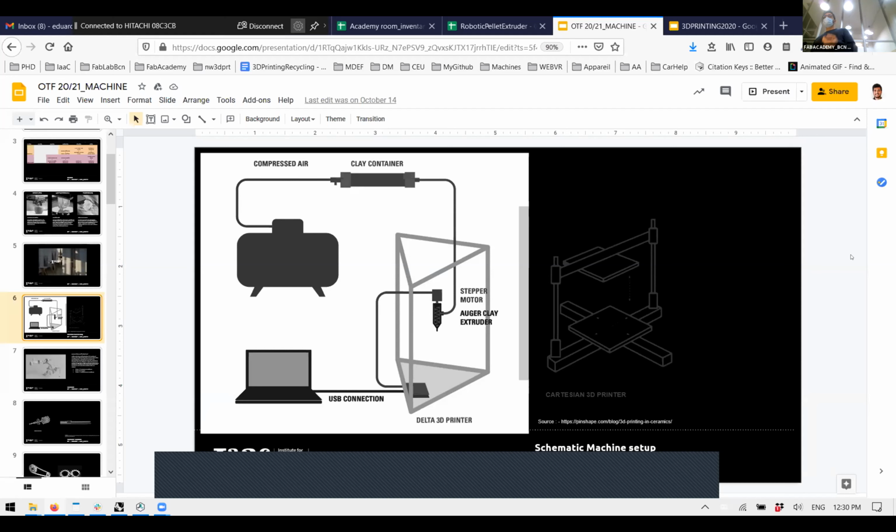So we jumped to smaller ones. That's a little bit limiting if you want to print large scale. But these cartridges are industrial adhesive dispenser cartridges that are industry safe up to 6.5 bars. And in general here we don't go below 5, just for safety. For example, have you seen the big extruder of the large plate one? That one reaches 10 bars. But that one is steel and aluminum, and it's another game. But the concept is exactly the same.